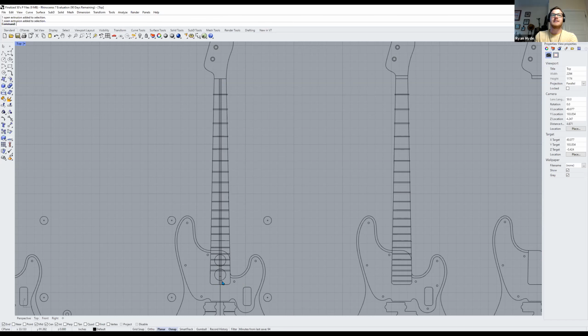And that's what's really difficult to get, because with a constant radius, you just get a radiused block with some sandpaper, and then boom, you're done. But if you're doing a complex radius, you have to start with one radius block at one end and sand a little bit, and then get your other radius block at the nut end and do a little bit. And you actually have to melt them together, and it's very time consuming because you can easily mess that up. And if you do mess it up, you're going to severely mess up how the fretboard plays and how the instrument plays.